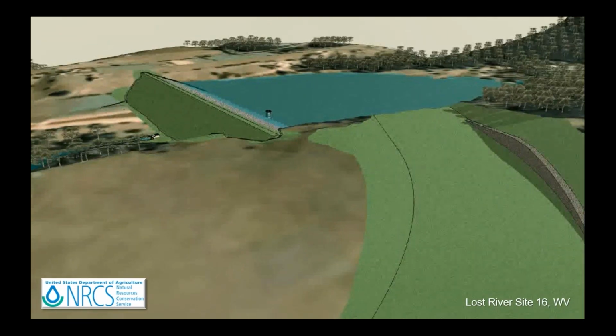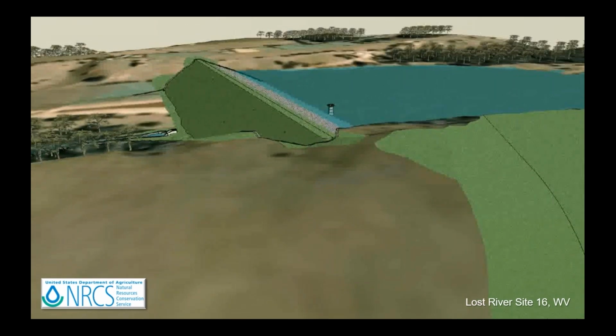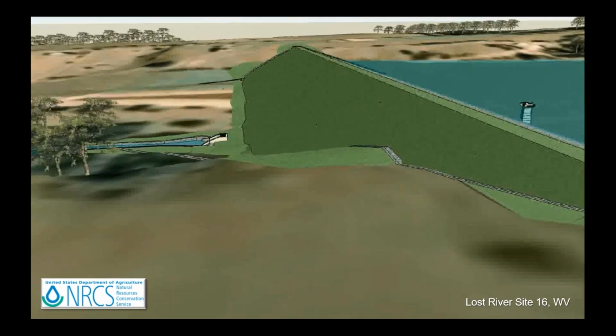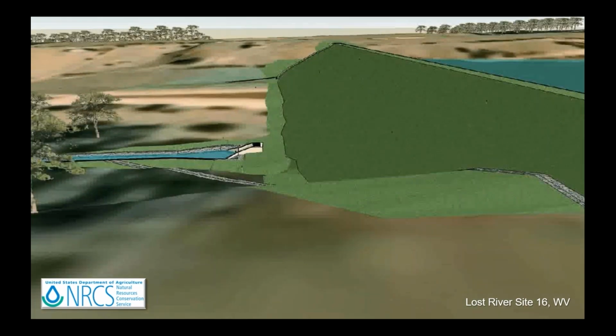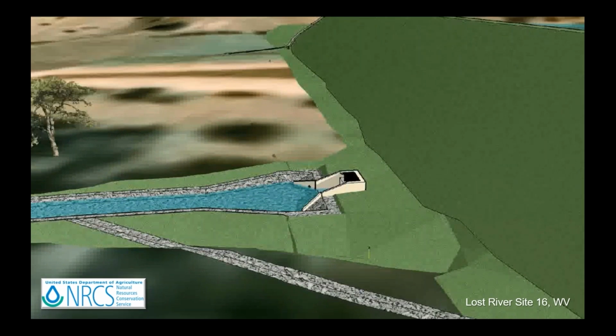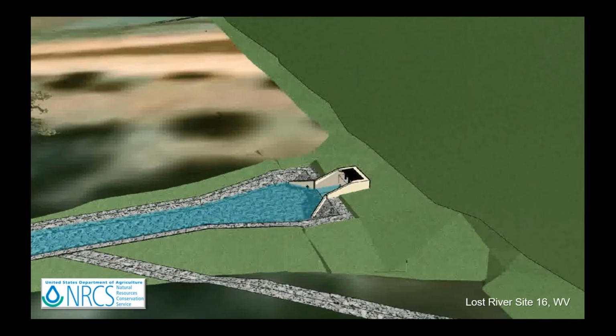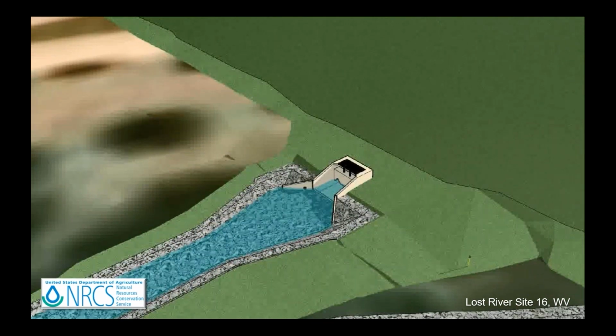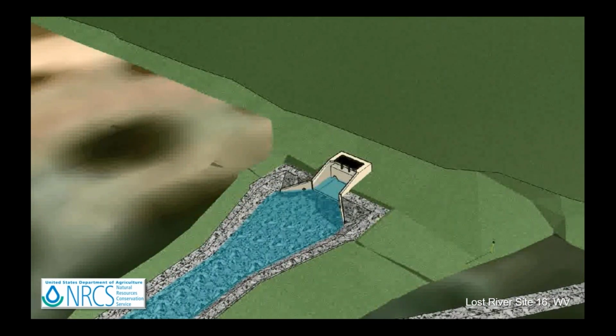We see the auxiliary spillway, and this one is an earth cut spillway, and it's discharging away from the dam, which is ideal. You see the contact of the embankment with the natural terrain is armored. That's the groin of the dam, and that's a place where runoff will concentrate sometimes. We have the impact basin here at the toe of the dam.